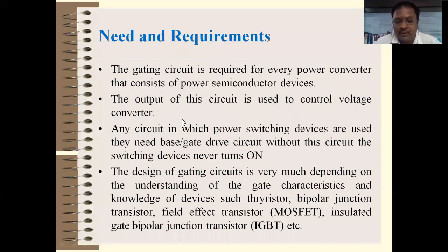Normally, for operating a transistor or any power device as a switch, an appropriate gate voltage or base current must be applied to drive the transistor, or maybe a MOSFET or SCR or TRIAC, any switching device, to turn on the device and put it into conduction with a very low on-state voltage. So the control voltages are normally applied to the gate to source or base to emitter of the device.